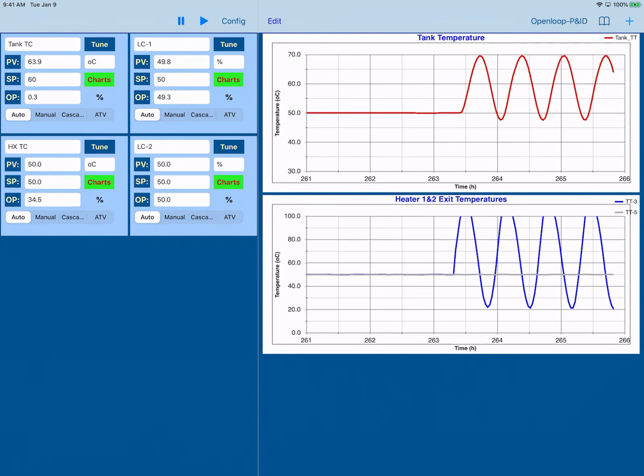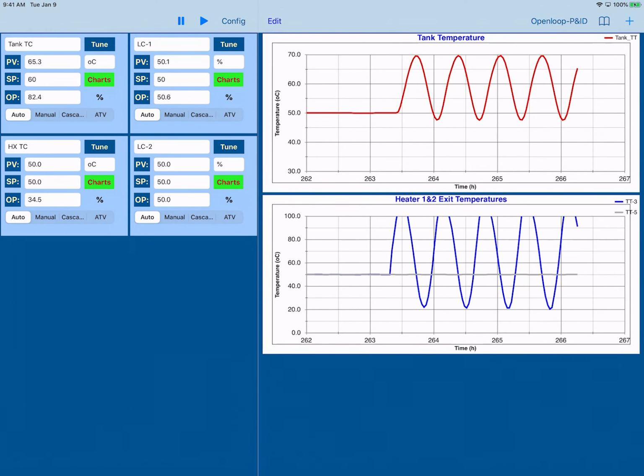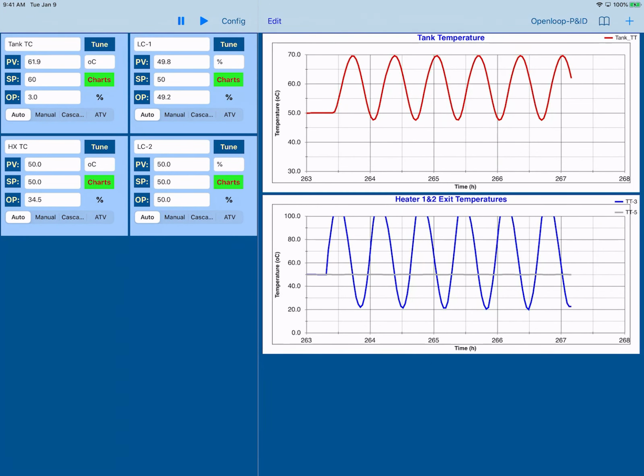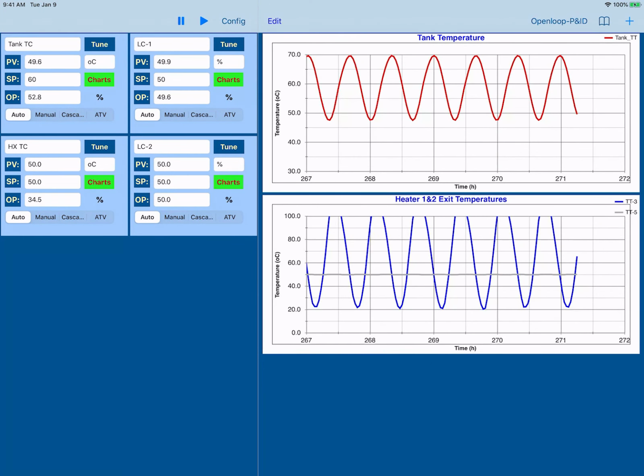So that's not very promising. There's obviously a limit for how low the integral time can be before we start running into self-oscillations. We now have two parameters in a PI controller that can be used to achieve optimal performance in a control loop. Both of these have limits to their values for the loop to remain stable. How do we select the right values for the two parameters? This opens up a major topic of loop tuning. We'll look in detail on some of the more popular methods in future videos.